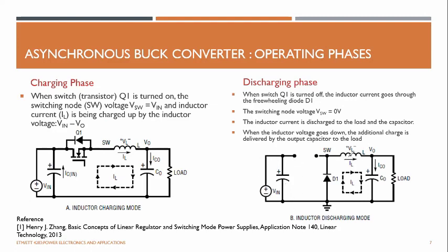Now, the inductor always tries to keep its current circulating; inductor current cannot be changed instantaneously. So the inductor looks to circulate its current because it cannot stop its current. It can pass this current through the capacitor as well as the load. The returning current can come through this diode, because it cannot go through here, since there's a bridge here, right? So it can't return from here.